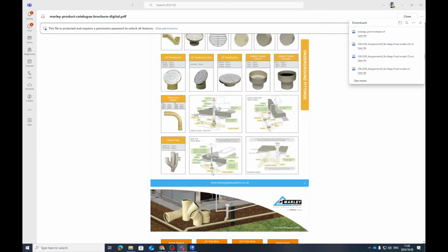Now, the head of the run, the head of the sewer must go to external air. Okay. So this one might just be called a stack, or S, or stack. That must vent to external air. The rest don't have to.